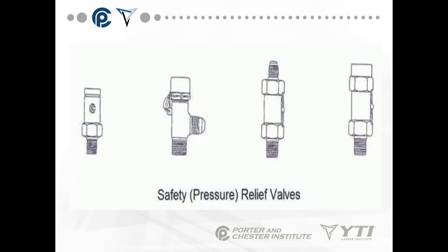We have different safety pressure relief valves. Different manufacturers do it in different ways. Okay, if your system has them, you have to find it, usually replace it, and correct the problem, evacuate the air out of the system, and recharge the system. Of course, after you leak check and everything.